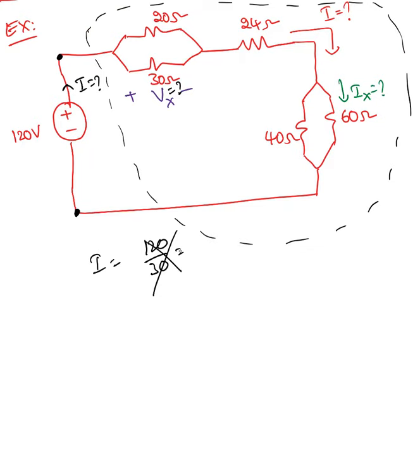Okay, so first thing we need to do is find which elements are in series, which elements are in parallel. Before that, if you want to, you can label the resistors, so that way you can easily recognize which elements we are talking about. Okay, now I can clearly see R4 parallel with R5. Usually I start with the resistor which is far away from the source. Why is that? You will understand better in future videos, in future examples.